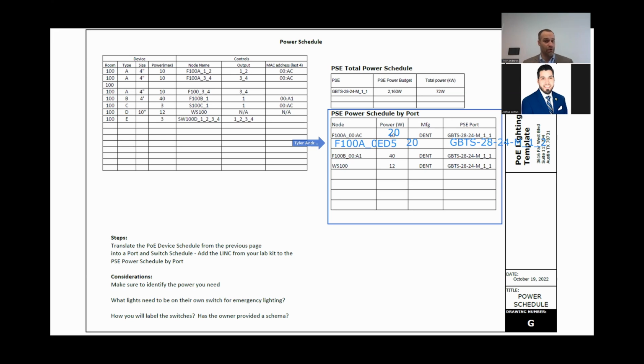No, the port that's feeding it is feeding the power and the color temperature. I guess my question is, does the temperature have a load? Is it a different LED? It is a different LED. In this case, we have two LEDs. You've got your 2700 Kelvin LED and 5000 Kelvin LED. They're both on the little LED board on the inside. And when I have full power on this one, it is the cool 5000 Kelvin light.